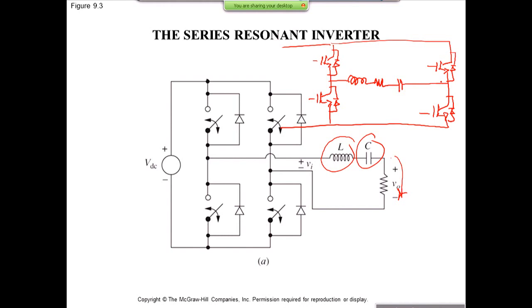And you could actually see that if you tune the system very well in terms of the quality factor of the resonance component and also the switching frequency, you can get a very nice looking sinusoidal current as well as voltage, because this is a resistor over here. So you can actually provide a signal with very low total harmonic distortion, as well as some ZVS and ZCS for some of the switches. So this is what we have already analyzed.